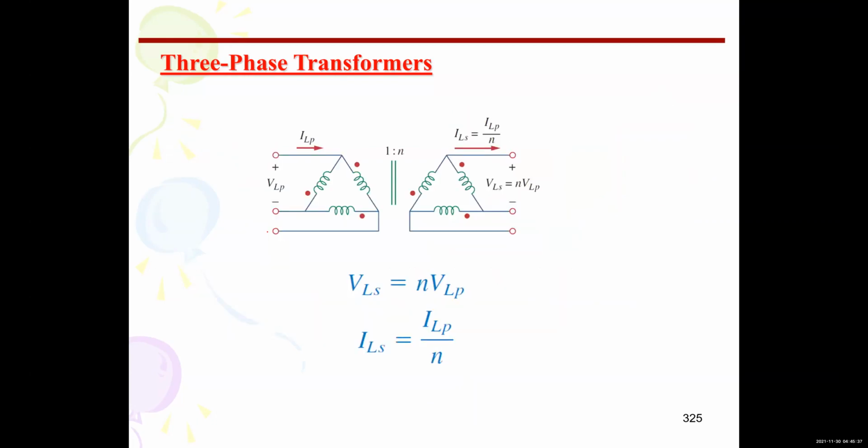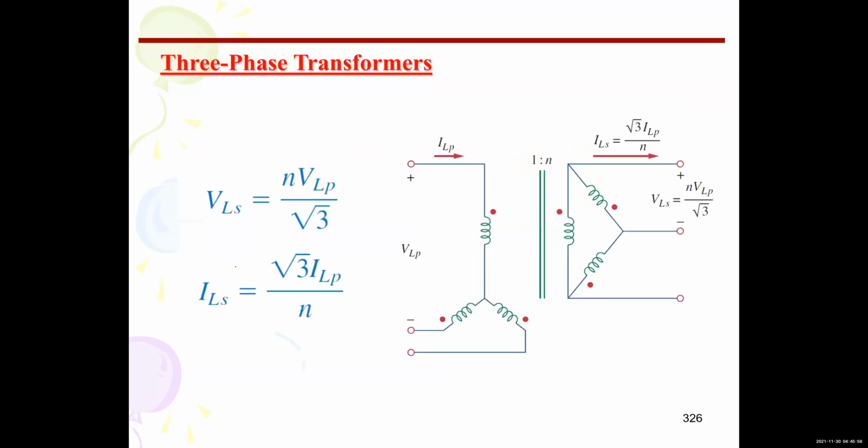For the delta connection, it's also the same story without going into the detail. Delta, but notice that the line voltage and phase voltage here are the same, whether primary or secondary. So the voltage ratio and the current ratio is equal to what? The turns ratio. The turns ratio. Is anyone not understanding here? There is nothing new.